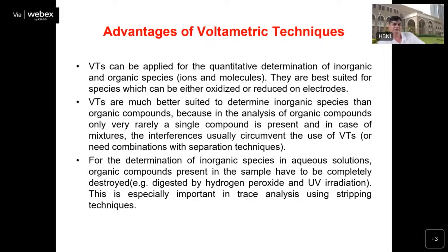But many times the concentration is very small, and you cannot detect it by naked eye, but organic compounds are there. If those organic compounds are there, they will interfere in all kinds of analysis. So that's why it's necessary to remove those things. That can be done using either hydrogen peroxide or even UV radiation, which sometimes helps us remove these dissolved organic carbons.